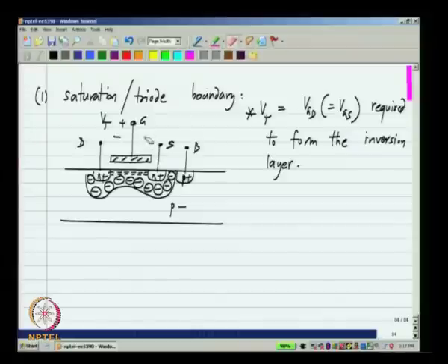Now, what is happening when you have Vd not equal to Vs? Let us say we do not have this connection. This is the normal case in a circuit. The drain voltage can be quite different from the source voltage. Okay. Now, let us imagine a case where a drain voltage is larger than the source voltage. What happens? The inversion layer will be thicker at the source side, okay, and thinner at the drain side. Okay. It will look something like that. Now, Vd greater than Vs means that there is less voltage across the oxide at the drain side than at the source side. Okay.